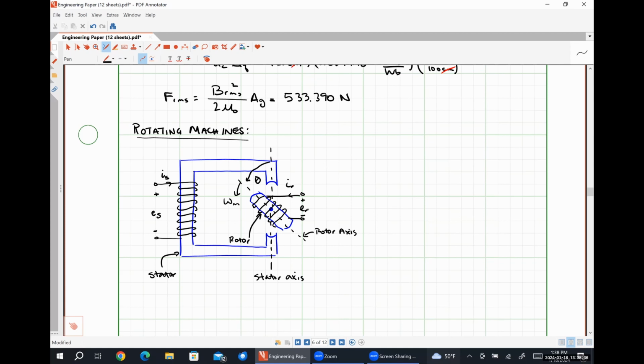If we apply an AC current to our stator and we don't have a rotor coil at all, then we have a reluctance motor, which is actually the type of motor that Tesla started using within the last couple of years for their drivetrains on all their electric vehicles. If we had a DC current flowing in our stator windings and we had a few other parts like a commutator and stuff like that, this would be representative of a DC motor. So this basic format is actually how all of the different electric machines that we're going to analyze for the rest of this class are generally laid out.